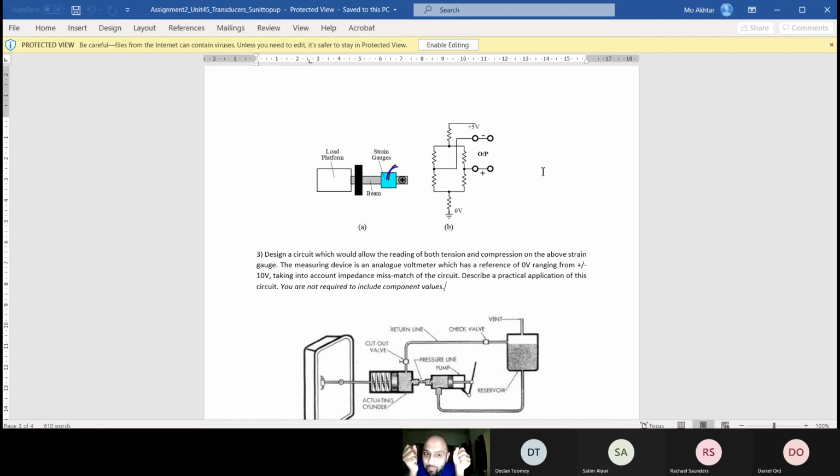That makes sense, people? And then the warning lights happen and all this stuff. Then the bridge gets closed if the beams are bending too much. That's an example. Does that make sense, everybody? Yeah. These are practical examples of strain gauges. They use them on bridges a lot. They're used in weighing scales a lot as well.